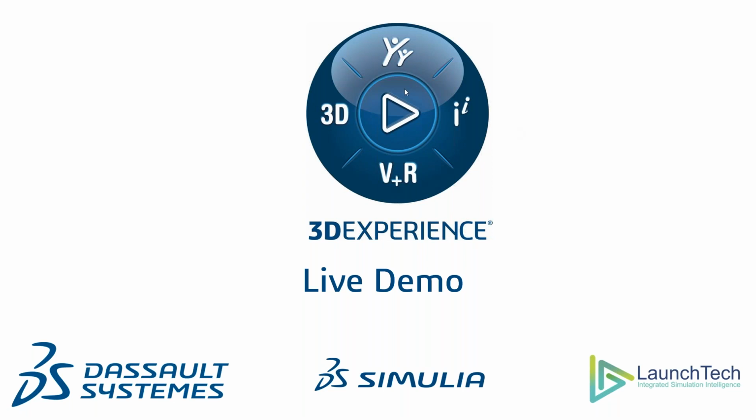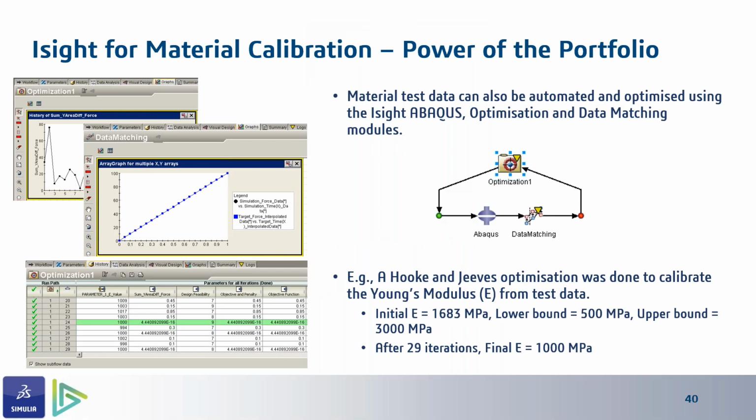Okay, so now I'll move on to the advanced topics of calibration. One way in which calibration can be achieved is by using Isight. In this case, let's just say I have multiple test data: uniaxial, volumetric, biaxial. They're very difficult to actually do the data matching and optimization on. So you could use Isight and it would give you the correct Young's modulus according to its optimization strategies.